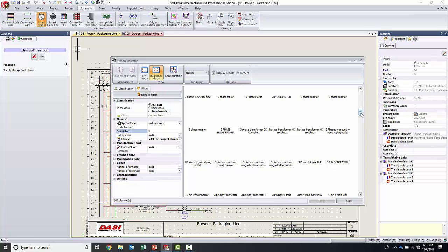With SolidWorks, if you push the board into SolidWorks, you can now make the contours using fillets and arcs and ellipses and holes without that issue, and then push the board back into PCB or Altium and have the capability of creating that board outline very quickly. So just as a side note.